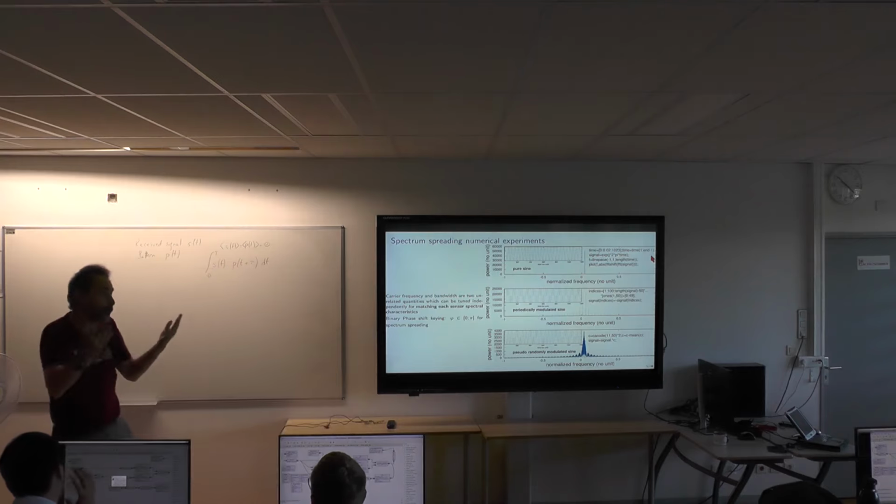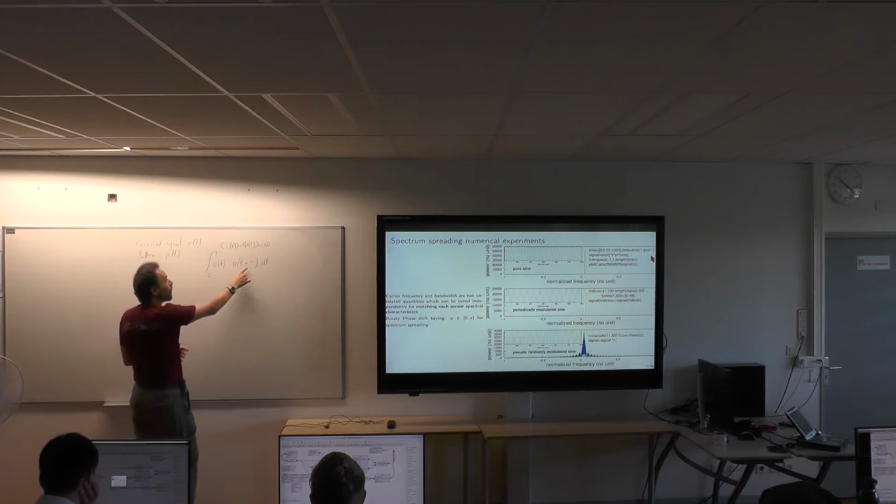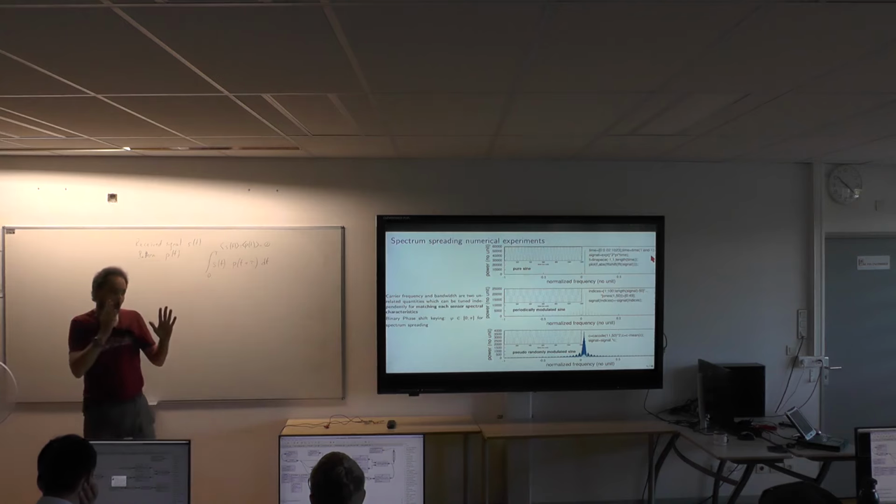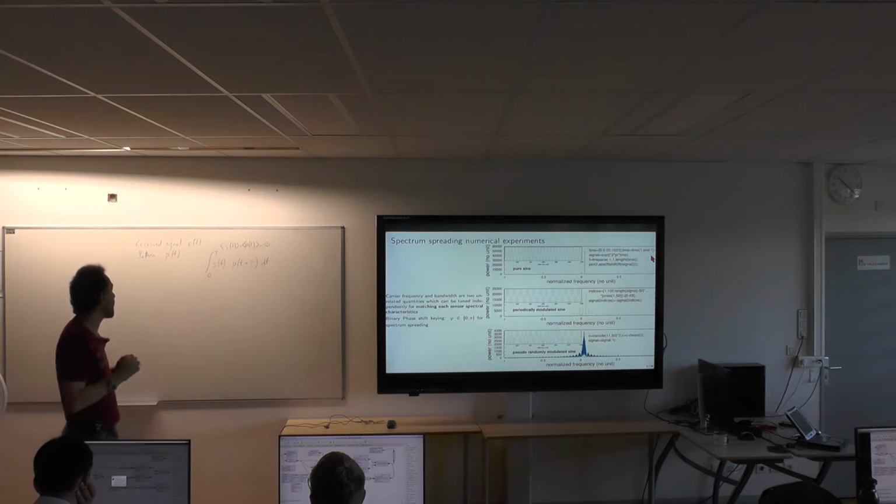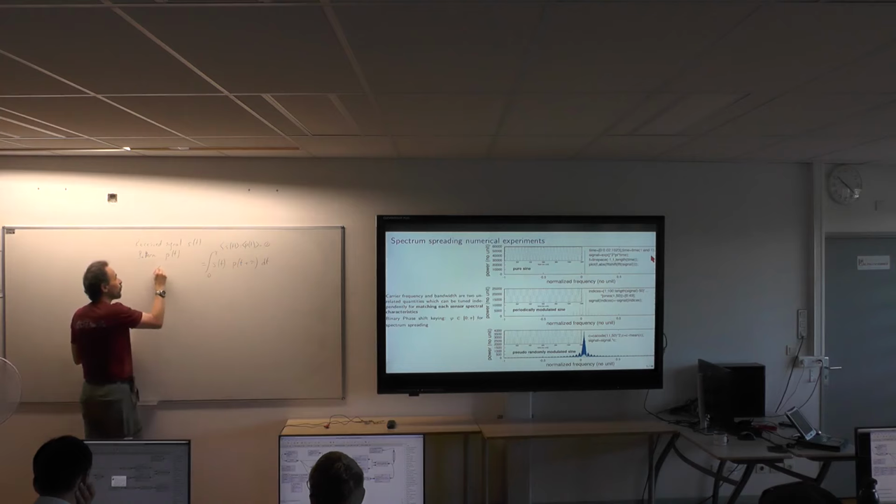So you will accumulate energy if you find a time delay tau where the shifted copy of the pattern matches the received signal. This estimator is called the cross-correlation between a signal and a pattern as a function of tau.